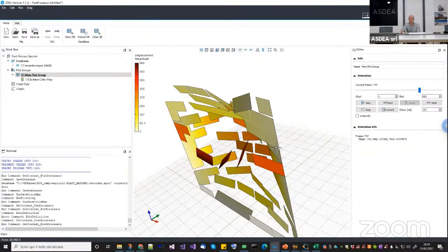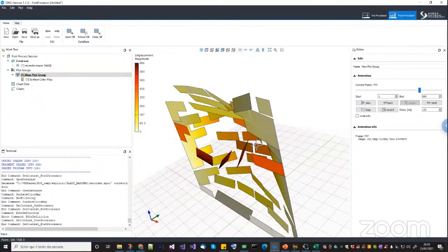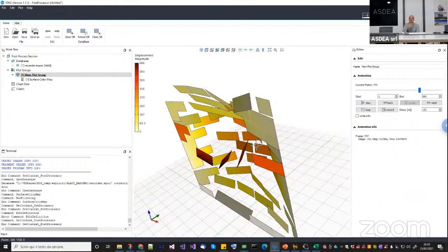Is it possible to move the current model from explicit to implicit co-simulation? You can, in the same simulation. For example, in this case, I did implicit for the vertical load and explicit for the second stage. You can even say, let's use implicit dynamics until my model converges, and if I have problems, I switch to explicit.